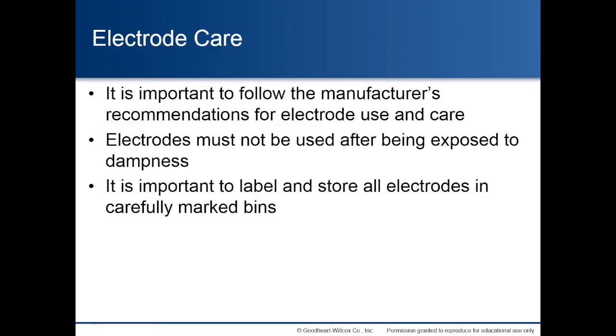Electrode care. It is important to follow the manufacturer's recommendations for electrode use and care. Electrodes must not be used after being exposed to dampness. It is important to label and store all electrodes in carefully marked bins.